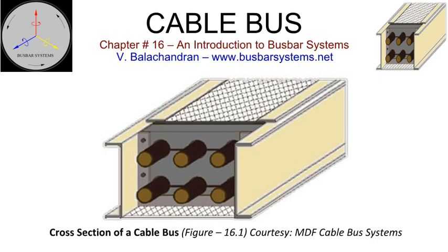It is the simplicity in design with the least number of accessories and robust construction that makes cable bus an extremely reliable product. The adoption of the cable bus system for a project is a matter of preference of the project authorities. Barring a few applications such as generator connections, a low or a medium voltage connection can be made either with bus duct or cable bus.